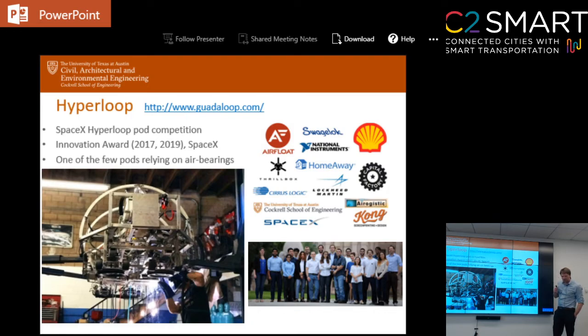The interesting part of this project is that we try to make pods for Hyperloop that would be based on air bearings. I still think personally that Hyperloop is very far away and it's not likely to happen in the near future because of a ton of reasons, including safety, economics, and all. But I think it's still interesting from a research standpoint because we have no idea of the performance of these air bearings at very high speed. We don't know, for example, how much airflow is required, what will be the stagnation pressure, and we were hoping that this competition would help.